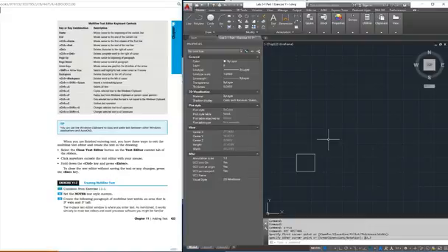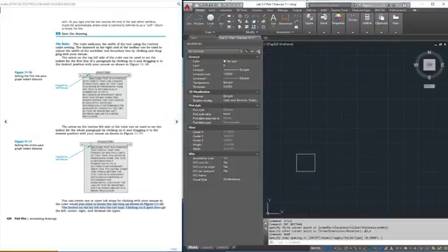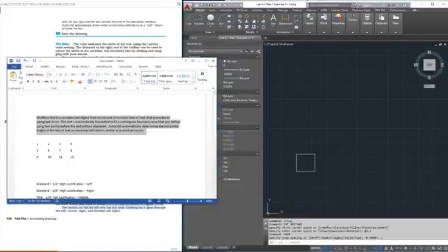Or if you wanted to make sure it was absolutely 3 by 3, one thing you could do is set your snap up to, say, 1 inch. Then your snap's turned on, and when you go to draw it, it's going to snap to every 1 inch. So I'm going to do some M text. And it wants me to type this big long box. So what I've done is I've typed this big long box right here, and this is the text.